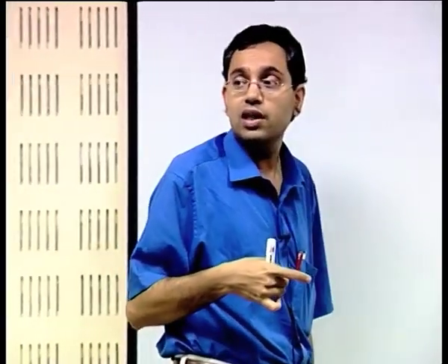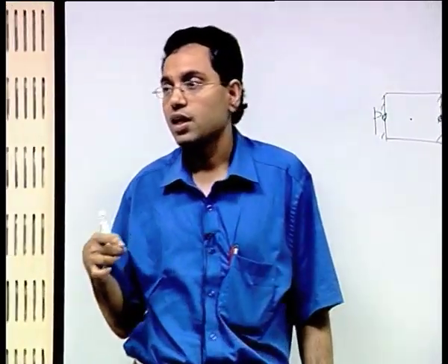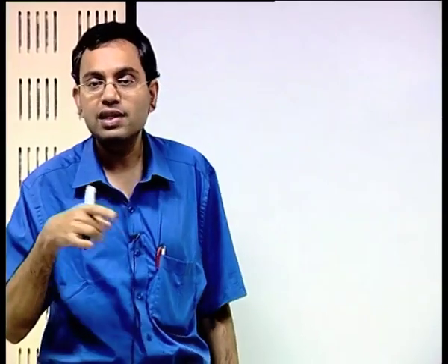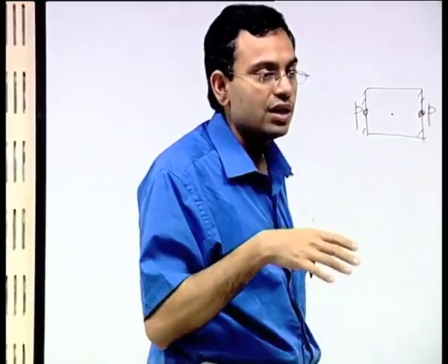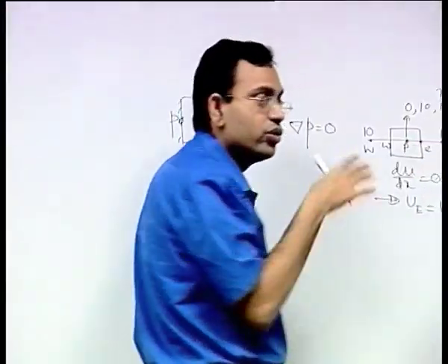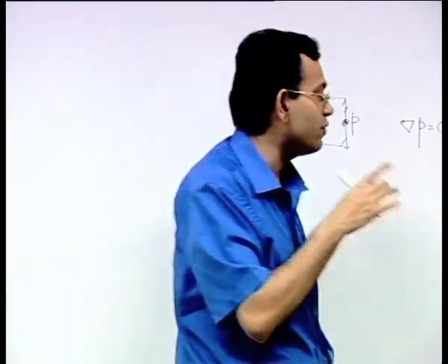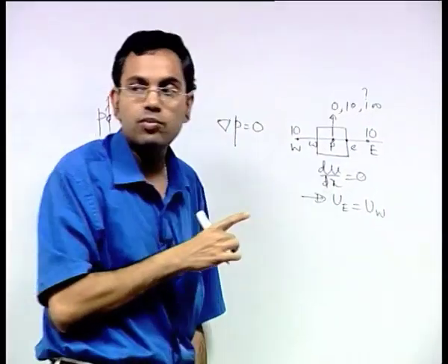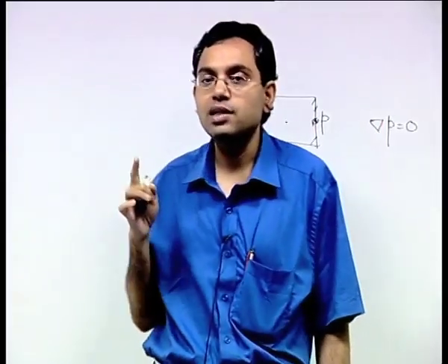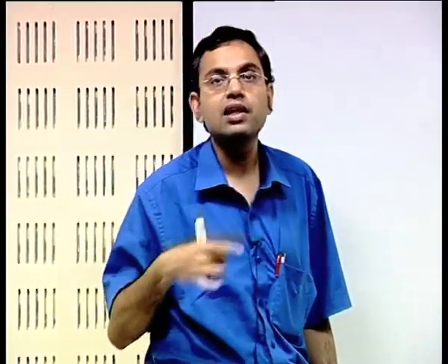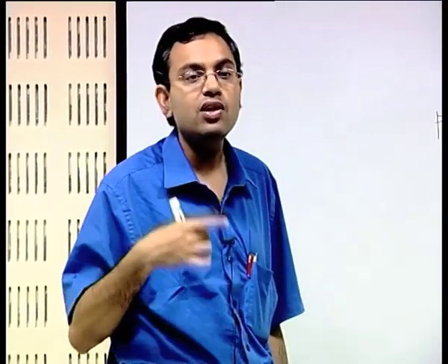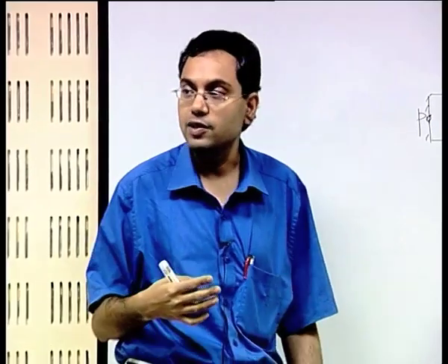So the question remains whether we have to go through the root of the continuity equation. Many times we do not have to. If you have a unidirectional flow, you already know the velocity distribution and it is just a constant value that you know already. So if you do not have to go through the root of the continuity equation, and just have to solve the momentum equation with dp dx equal to 0, then you do not have to bother about staggered grid, because then it is an issue of pressure interpolation only and that need not be taken care of when the pressure gradient is 0. So that is what we have to keep in mind.